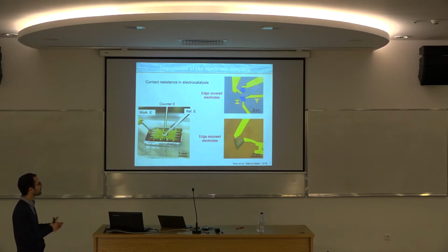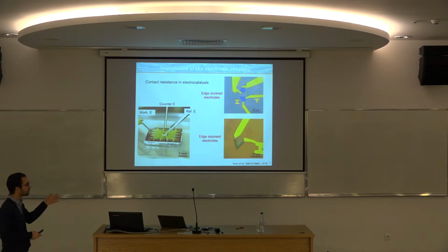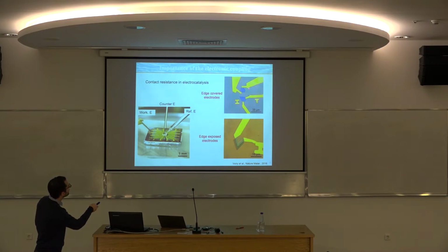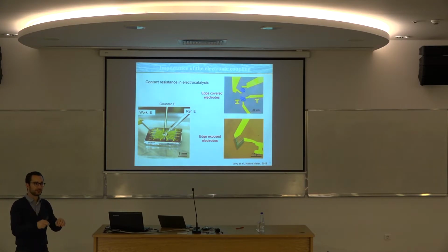And actually, I think this is one of the first reports where we gave some values, or at least showed the influence of the contact resistance. So with the same strategy as before, we were able to transfer a single layer of MoS2 that was CVD grown, so the contrast is not so good, but you can barely see some MoS2 here on the silicon dioxide wafer. And then we converted locally the contacts, then we put the gold contact. We cover everything else with PMMA, so only one flake is exposed, and we contact it with 2 electrodes so that we can sweep the device.